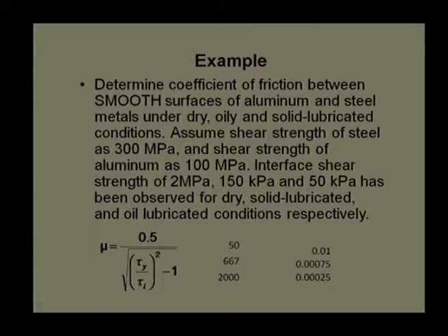From an overall economic point of view, if I consider the cost of lubrication, the mechanism of lubrication and the accessories required for it, I can reject the second and third options. I can say that a coefficient of friction of 0.01 is very, very low. We can tolerate this, we can go ahead with this.